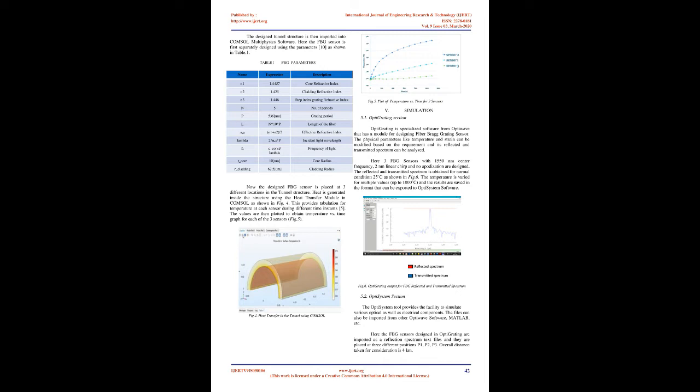The output from each sensor will be the same, i.e. the reflected spectrum of all the sensors is at the same center wavelength. But during the condition of fire, as in Fig.2, the temperature reading at each sensor will vary, so their reflected spectrum shifts away from the output obtained at the ideal reference value, 25 degrees Celsius.